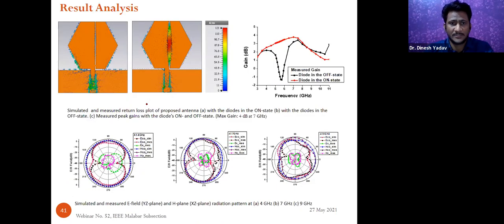Okay, so these are the radiation characteristics of this antenna, and the surface current and gain. Although the gain of the ultra wideband antenna is nearby 4 dB, which is reasonably good. But yes, if we go for the narrow band, we will get good gains for the antennas, nearby 7 to 8. So gain enhancement technique we also could incorporate here, but again it's scope for the future.